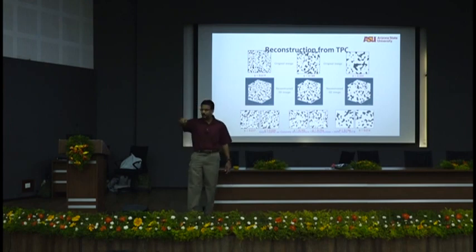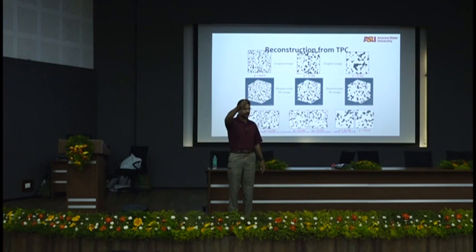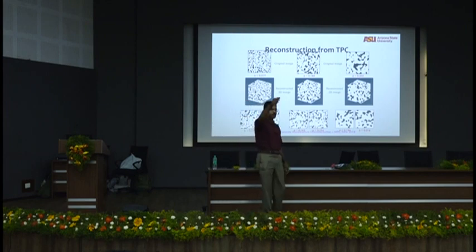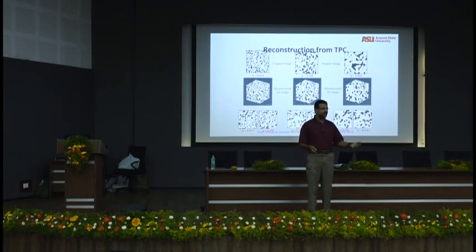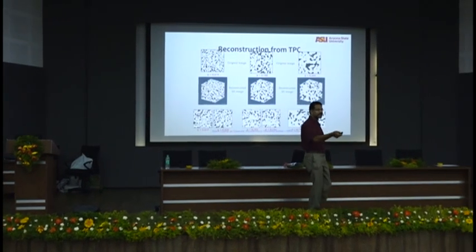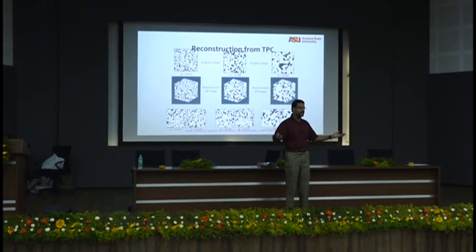Remember the curve that I showed you yesterday? Correlation function: you throw in lines of different lengths, and when you throw a point, what you get is a porosity, and you see the curve plateauing off. The value at the plateau is the square of the porosity. You draw a tangent at the point of start, and where the tangent meets the asymptote, you come down, that's a critical length. You take the first derivative of the function with respect to that length, you get one-fourth of the specific surface area, right? We did that yesterday.